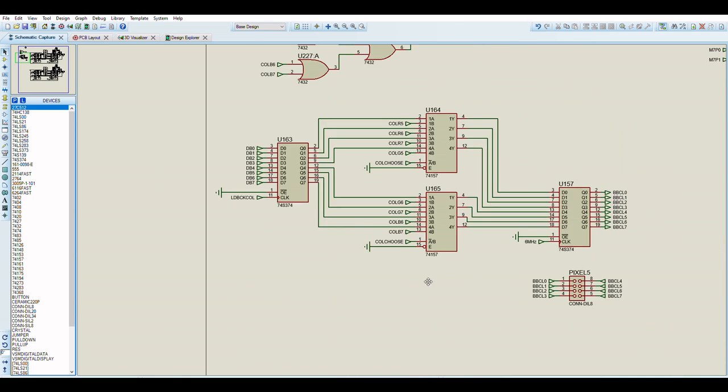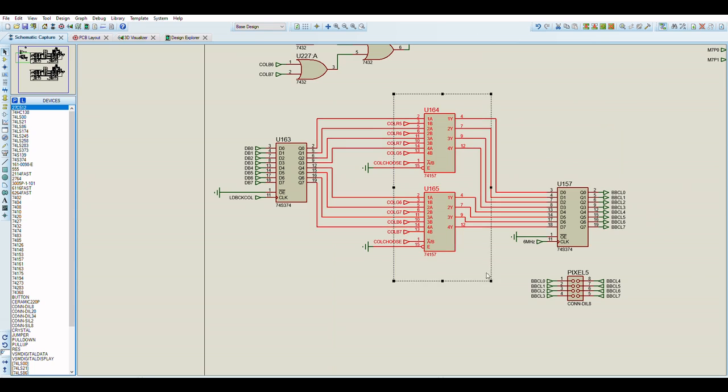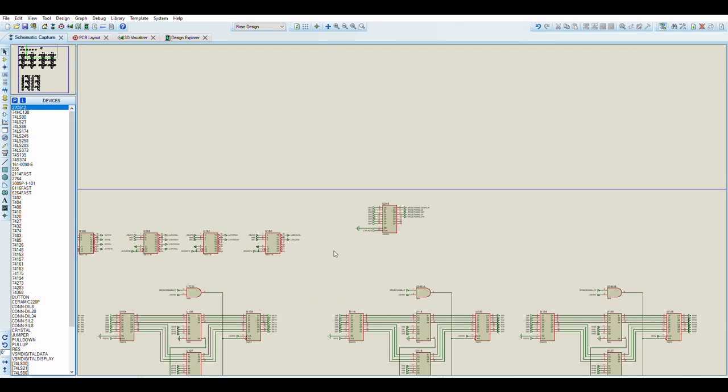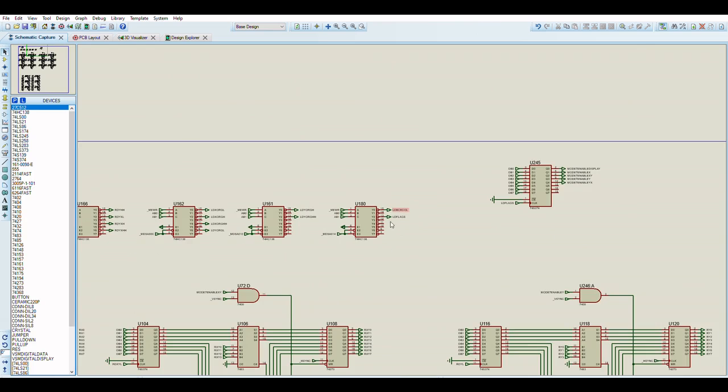it goes through this demuxer here, which either has the option of using the loaded background color as a latch. Okay, so this is the background color that's loaded from this signal here, which was from the I want to latch the data for a background color here, or the flags. Right. Flags are loaded by this latch. The background color is loaded by this latch.